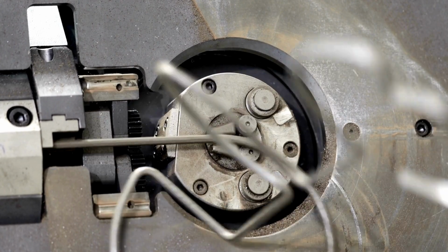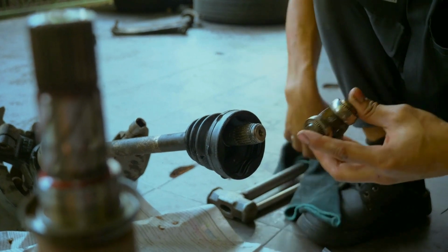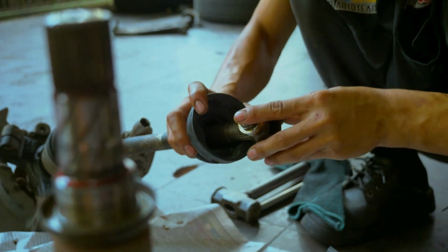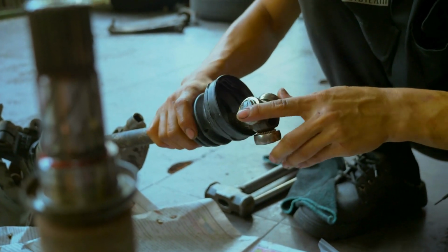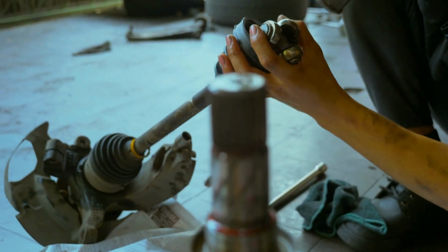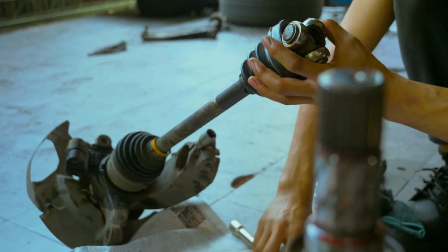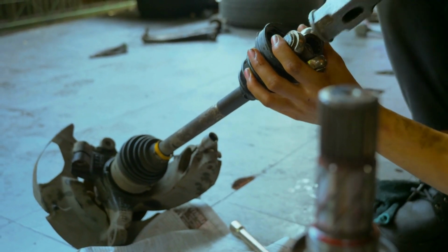Torsion in a steering mechanism refers to the twisting force applied to a torsion bar, which is a key component in some power steering systems. This torsion bar is connected to the steering wheel and transmits the driver's turning effort to the steering gear, ultimately steering the vehicle's wheels. In some systems, the amount of torsion in the bar is used to adjust the power steering assistance.